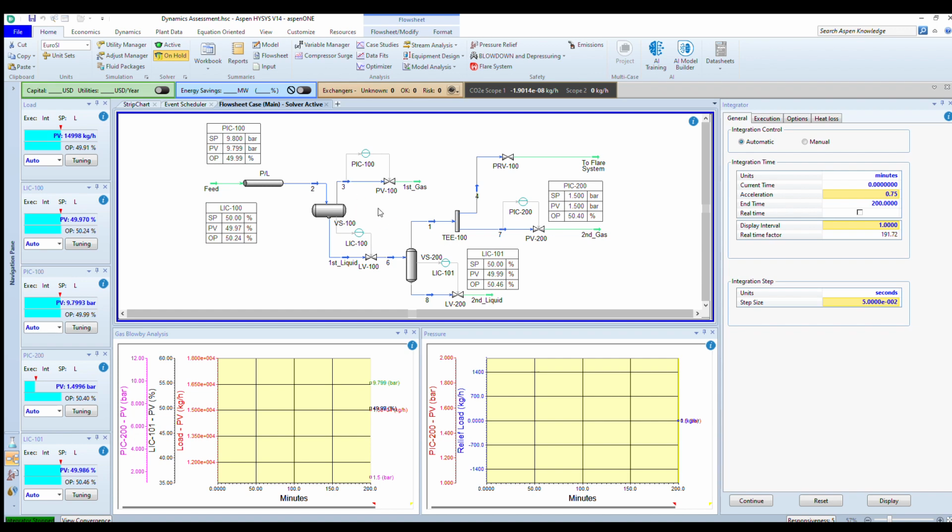Basically, the existing basic process control system is not a substitute to replace the pressure relief devices, but it considers an element of reality, because at the same time this control valve is functioning and the overhead gas control system is functioning.